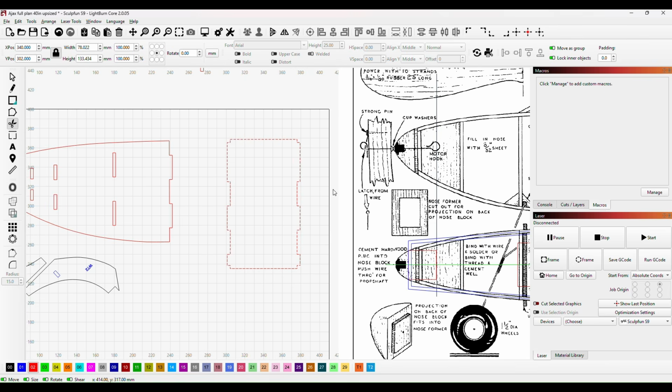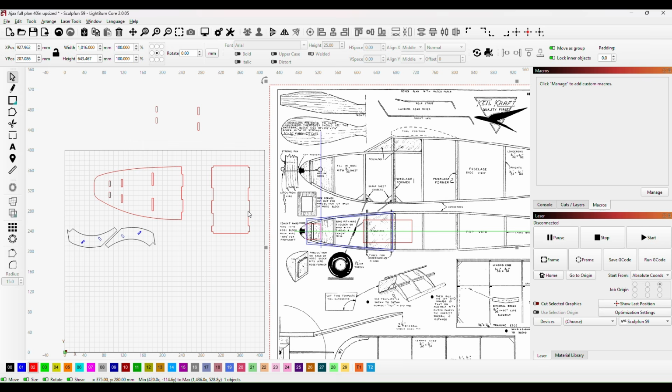Okay, so that is the start of our former. And the next thing I'm going to do is I'm going to now cut a slot in the bottom, which is going to be the shape of our battery hatch. So the way I'm going to do that is, the battery that I've got is 20 millimeters thick, but it's then got some Velcro on either side, Velcro on the battery and then Velcro to hold it in place.